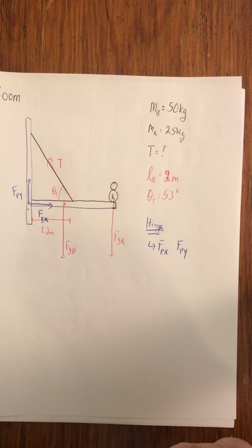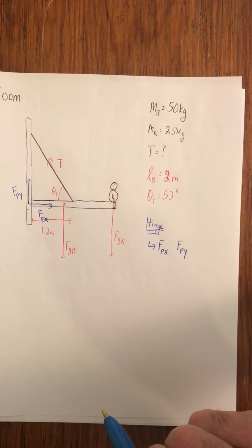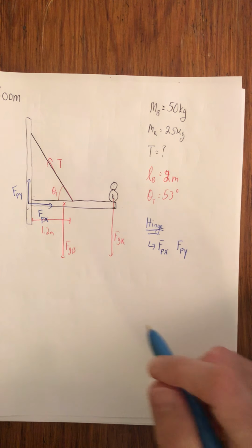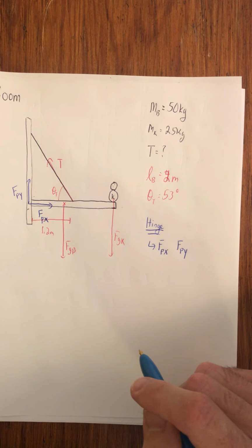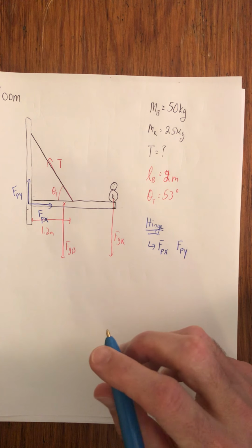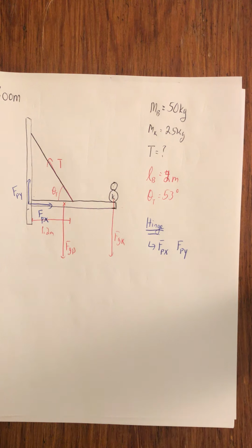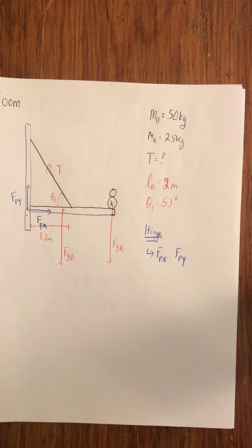Hopefully, if you remember in the past, when we calculated forces to be negative, there were two implications. The first was that we put it in the wrong way in our free body diagram, or the second was that that force didn't exist. In this case, if you calculate those forces' magnitudes to be negative, that just means you put them in the wrong direction in your free body diagram. There's no need to redo the problem. You would just analytically state that and off you would go. So the nice thing is the math is going to help us out here. So let's get to this.